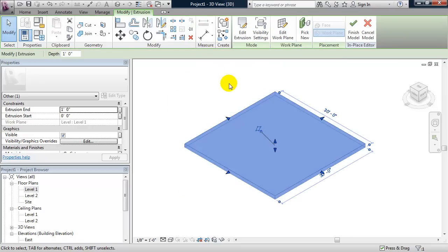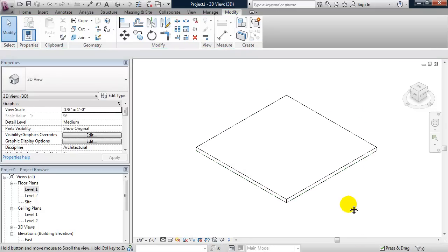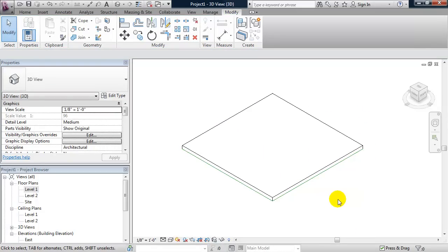Now Revit will allow you to make multiple extrusions as one model. Other types of generic models like sweeps and blends can be made all as one model. So that's why we have to click on the green check mark once again to finish the model. Okay, so the test now is if the grid lines move, will the model lines move, and then this generic model move as well.